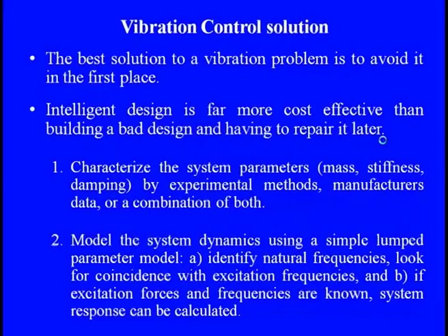Sometimes we use a simple lumped mass, or sometimes a continuous structure according to the system itself, and identify the natural frequencies: first, second, third, or higher harmonics.